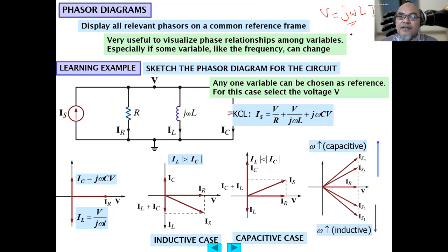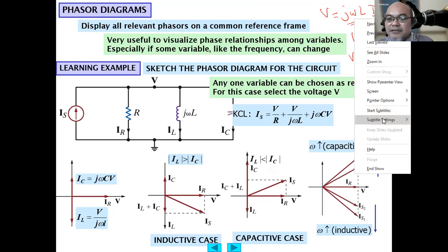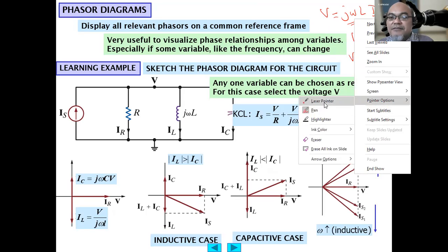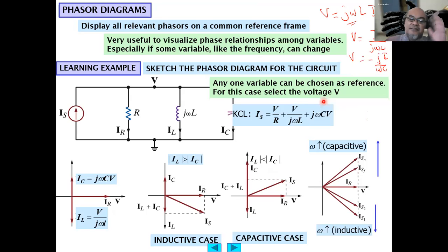In the capacitive circuit, voltage equals current divided by j omega C, or minus j I divided by omega C. So here voltage is lagging the current by 90 degrees, because this is minus j. Okay, this is to remember. So you can remember it by using the formula of impedance for capacitive and inductive, if you have forgotten which one is lagging or leading, voltage or current.